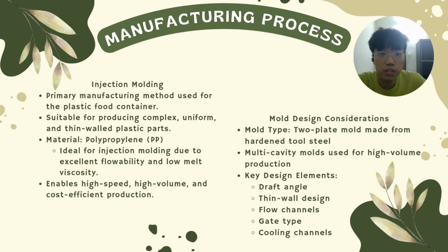For mold design considerations, the mold type is a two-plate mold made from hardened tool steel, and a multi-cavity mold is used for high volume production. The key design elements for this process are draft angle, thin wall design, flow channels, gate design, and cooling channels.